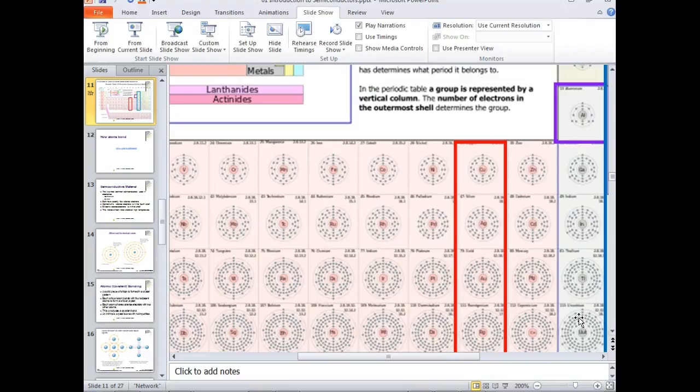But why? It's cheap, and we step the voltage up so high that the current goes down, so we can afford that. By the way, the rule of thumb is that you increase the gauge size, not the number. Gauges are kind of strange. As the gauge size goes up, the gauge number goes down.